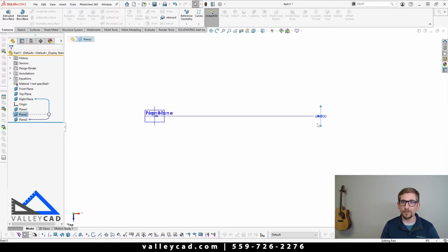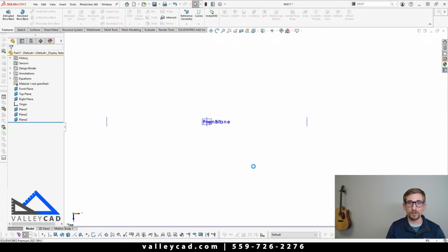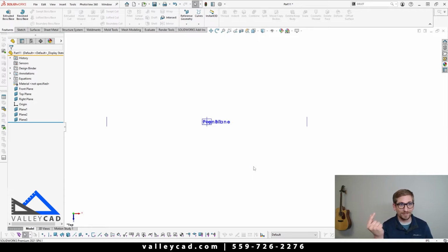Then I'm going to do the same thing over here with this 60. I'm going to double click on that one. We'll say that this one equals OAL, divide by 2, and simply say okay. So you'll see that automatically calculated that to be 75 for me.